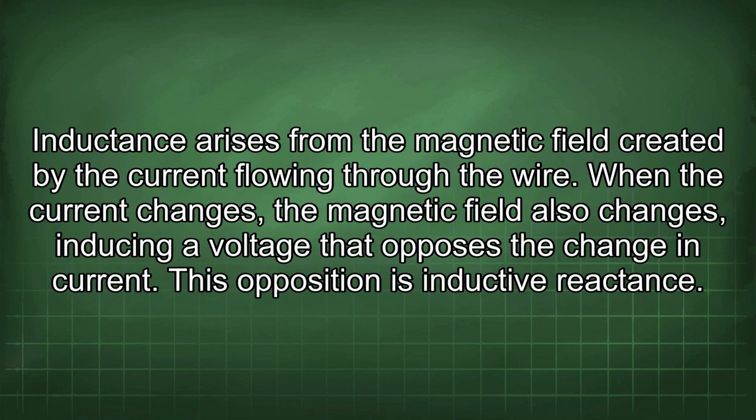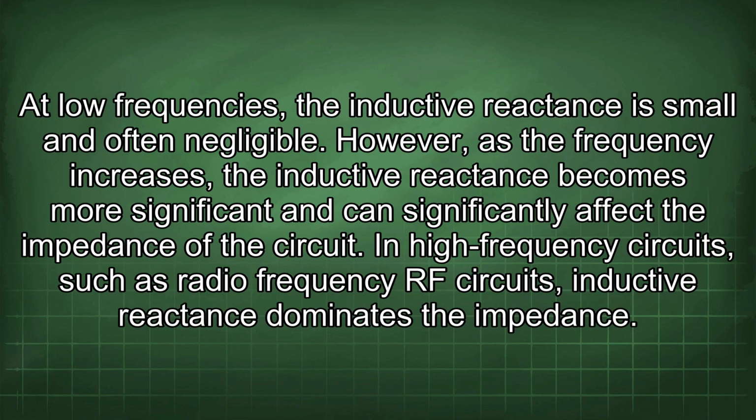Inductance arises from the magnetic field created by the current flowing through the wire. When the current changes, the magnetic field also changes, inducing a voltage that opposes the change in current. This opposition is inductive reactance. At low frequencies, the inductive reactance is small and often negligible. However, as the frequency increases, the inductive reactance becomes more significant and can significantly affect the impedance of the circuit.